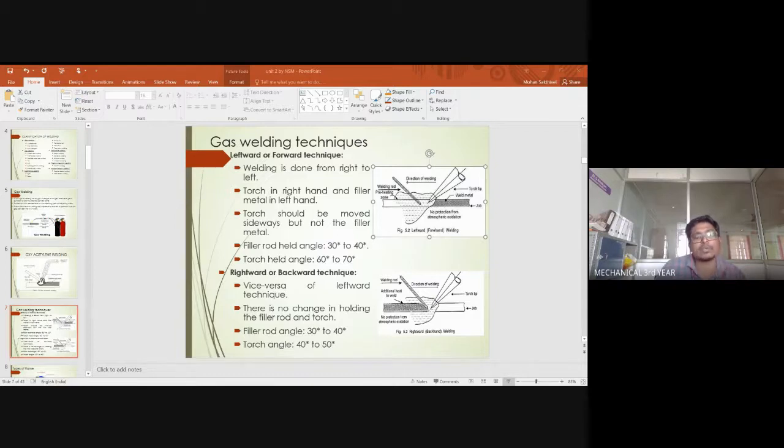The density of the molten metal is higher than the density of your flux coating, and that is why the molten metal goes inside, whereas the slag is present over the top. Since the density of the flux is quite a bit lower than that of the metal, the slag stays on top. Can you understand with the help of the diagram?